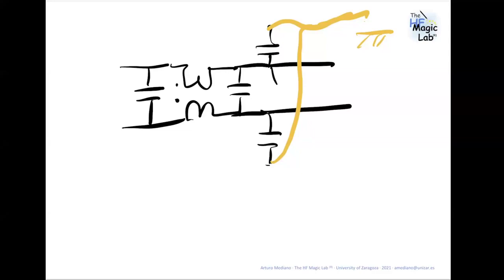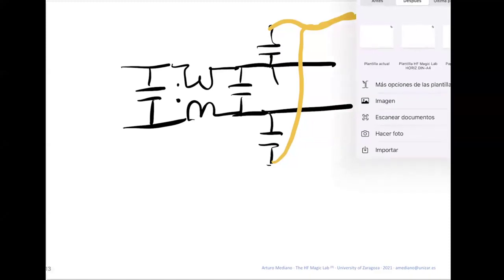Let's see. Is it better to use a ferrite bead instead of an inductor? No, it's different. Remember that, I don't know exactly where you refer to use a ferrite bead instead of one inductor. Obviously, in the output of the buck converter, it's impossible because you need to store energy and you need one inductor, no? And if you are considering some kind of filtering, this is the same idea. Remember, with one inductor, in theory, you have ohms related with omega L. There is no dissipation. Obviously, you have a small resistance that is related with the copper or losses in the core or something like that.